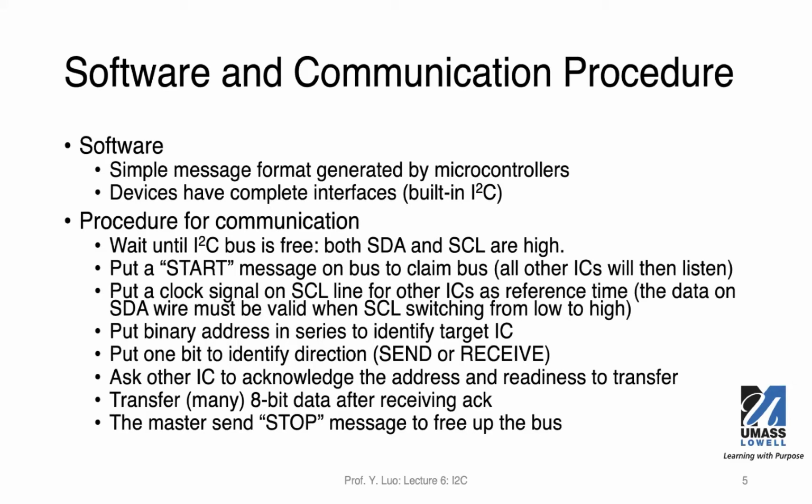The first step is to wait until the I2C bus is free. The indication that the bus is free is when both SDA and SCL are high. We'll see some illustrations later. After that, if one side, especially the master, is trying to communicate, it will put a start message on the bus to claim the bus. That's the step where the master claims the bus and gets other ICs ready to listen.